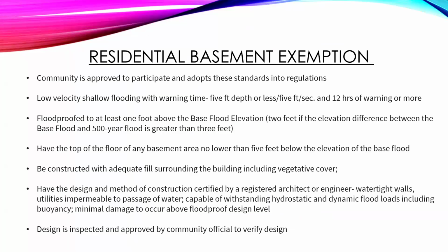Just real quick here, as we're getting closer to the end, the residential basement exemption. So basements are something that come up a lot in Kansas. People want to build them in the floodplain pretty frequently, or even expand existing ones frequently. So FEMA did at some point way in the past start this residential basement exemption program.